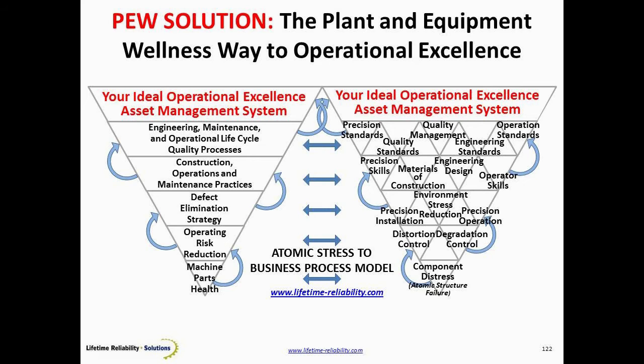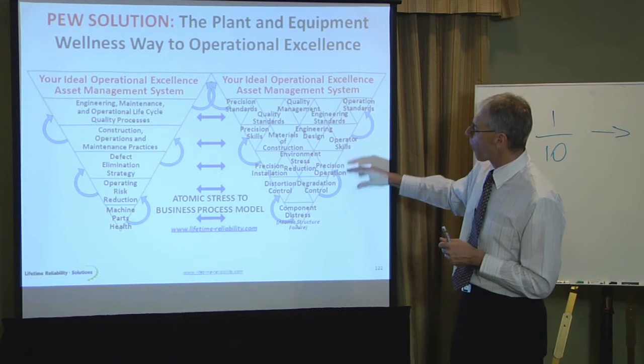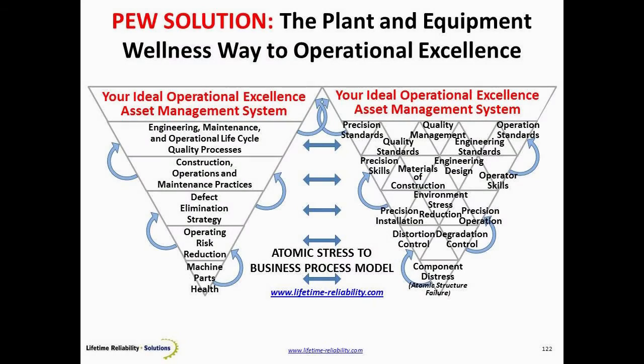So I've got to start controlling degradation in the operating area and in the maintenance area, and distortion when it comes to rebuilding and running it and installing it. And then I'm going to have processes and procedures that involve precision maintenance, precision operation. I've got to control the environment that part is in. If my part is inside of the machine, then the local environment around it, the lubrication, the temperature, the interference fit, the distortion, the overload, I've got to control those, because the part breaks, then the machine fails.